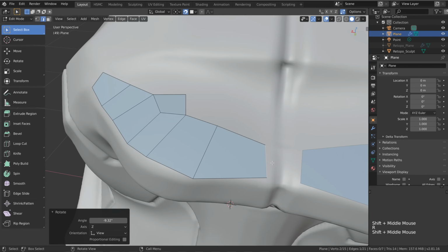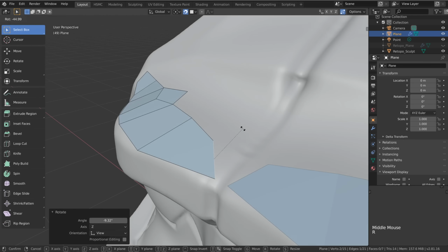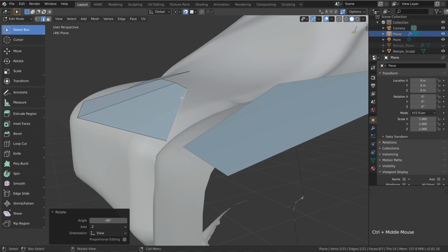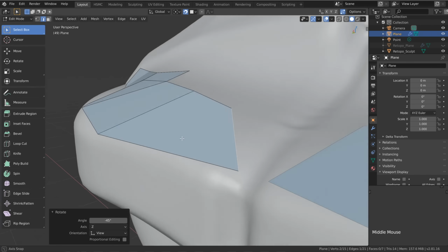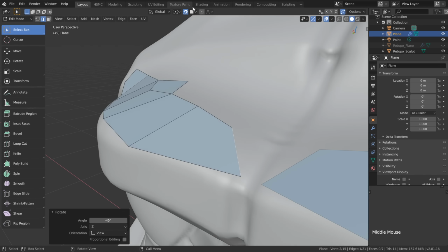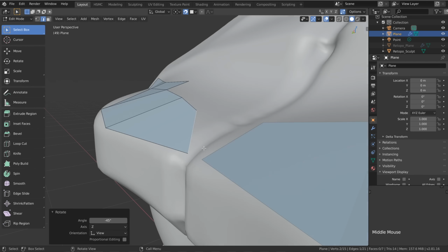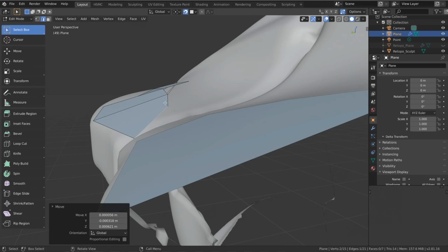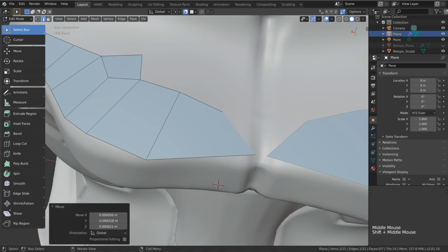Now something that's important to note, if I rotate these and maybe try and find a different angle here, you can see that the geometry is no longer conforming to our snapped surface, our faces that we have it currently selected to. G for grab, however, does. So if scaling or rotating, it's probably a good habit to just nudge it slightly with G and then just let go. And now we can see both of those vertices on that edge have been put into position,